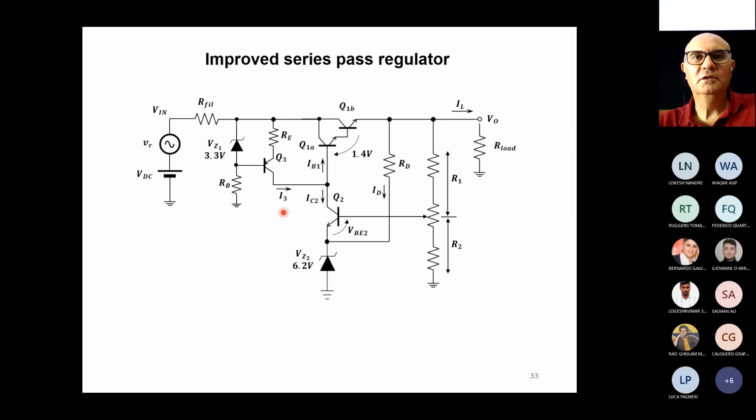So now we need what? 4 transistors, well, or let's say 3, because we can buy directly a Darlington transistor. If you want, you can buy a single transistor which has 3 terminals, as you see here, but has a Darlington configuration inside of the case.